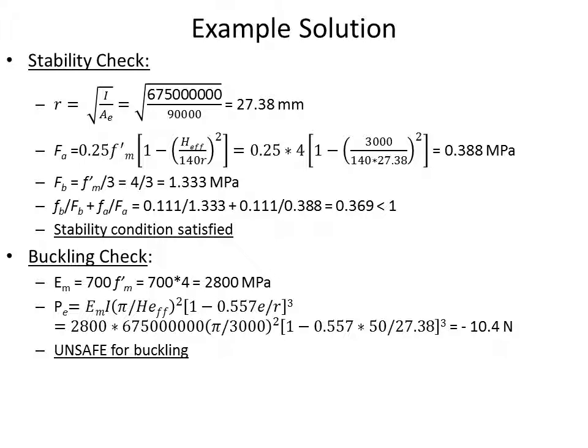So it has already a high buckling length, which is, sorry, 3 meters, not 4 meters. And it has a high eccentricity together, an eccentric load. I mean, if the load was concentric, life would have been different in such a case. But you are having an eccentricity and a high wall without lateral support, you are having a problem here.